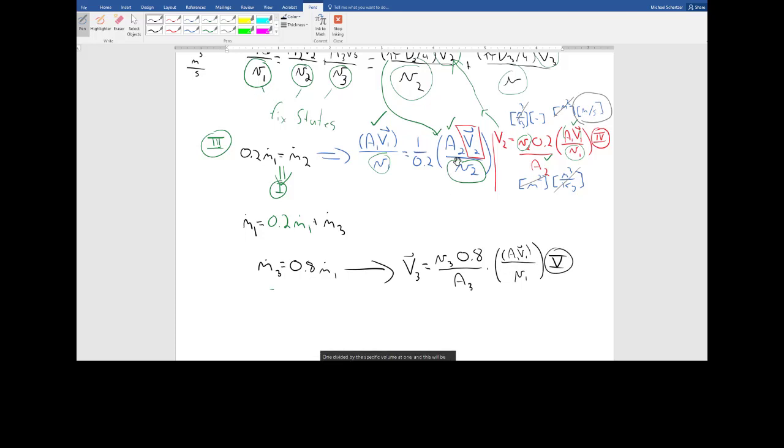So if I look at this equation, I start to do some accounting, right? I need to fix the state to get V3. A3, right? This is pi d3 squared over 4. A1 V1 is given. I need to fix the state to find the specific volume at 1.